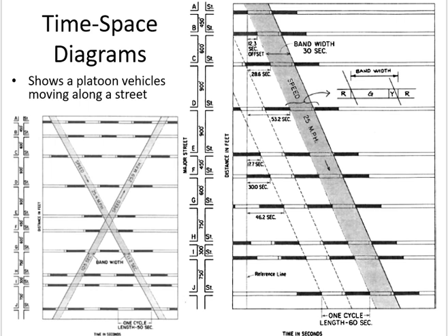Still you can use. So if your offset was exactly 60 seconds, let's say, and cycle length is also 60 seconds, you subtract the cycle length. 60 minus 60, you will get what? 0. So the first green is at the reference line. Fine, no problem.